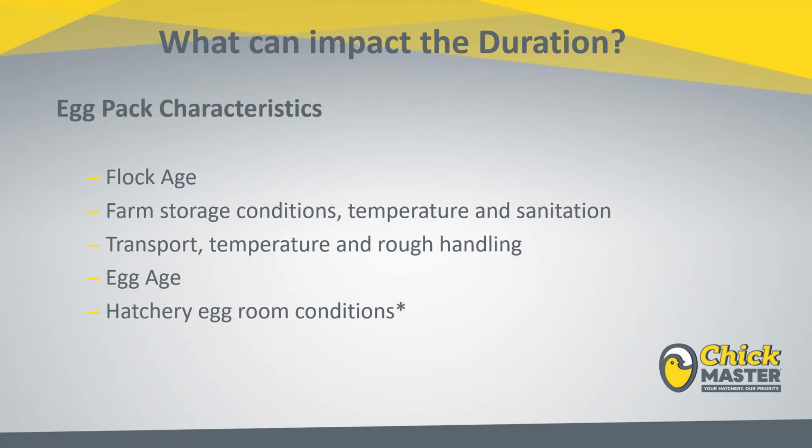So if we essentially, bottom line, look at it from that perspective, a probe like that used with a wick and a water bottle, that probe will last a long time in that hatcher machine, whereas an RH sensor, a relative humidity sensor, is a lot more sensitive. If they get a lot of water on them, it takes them sometimes a couple of days to completely dry out. They're also not very durable. So if they get hit with hot water or high pressure water, they can get damaged pretty quickly. And so that's why we see more consistency with a wet bulb in a hatcher, just simply because of the life expectancy of the probe.